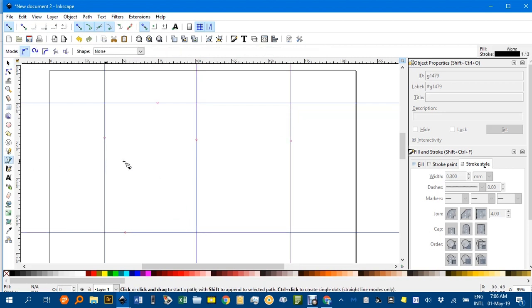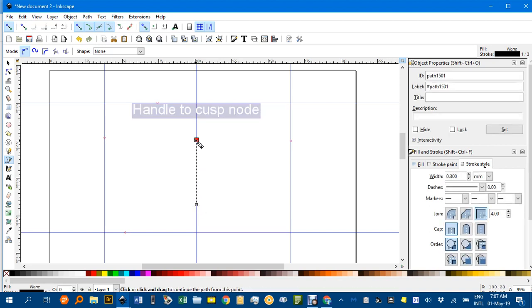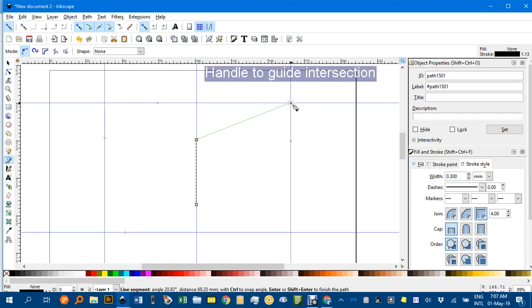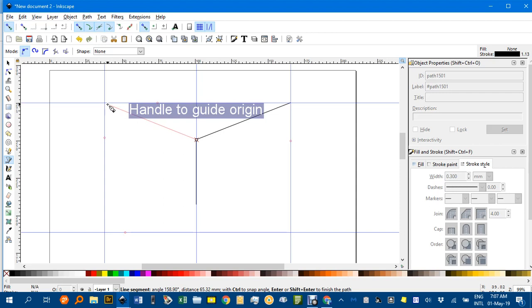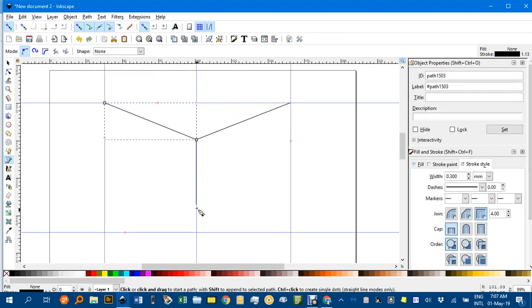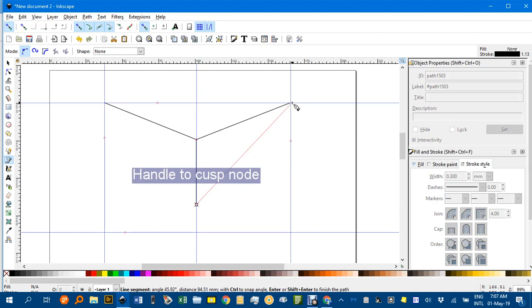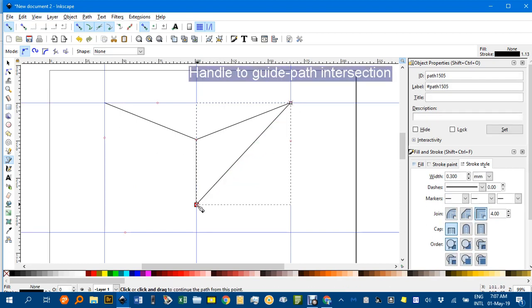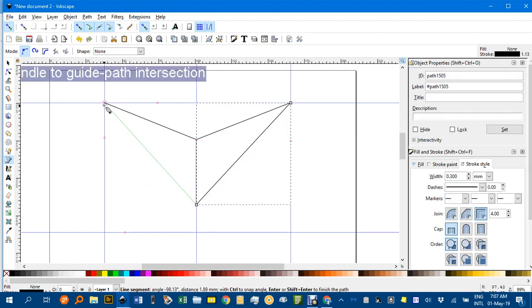Now with the Bezier pen tool, let's draw a line. Oh, it can be there, that's okay. Click, click and enter. Then from the top to each vanishing point here, click, click, enter. I'm just doing them all as line segments. And from the bottom of the line, click, click, enter, click, click, enter.